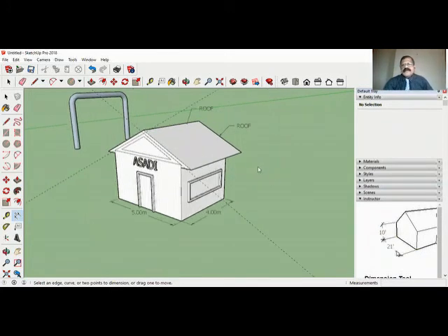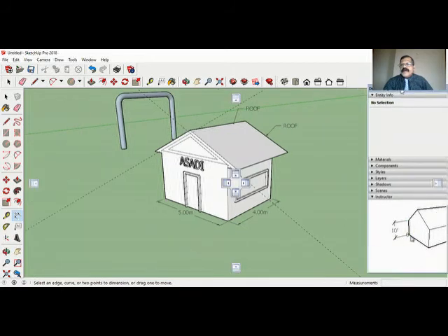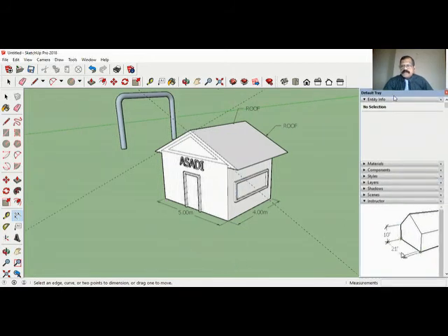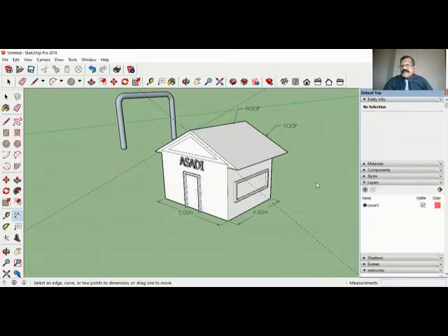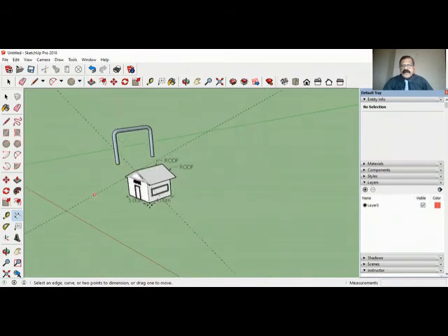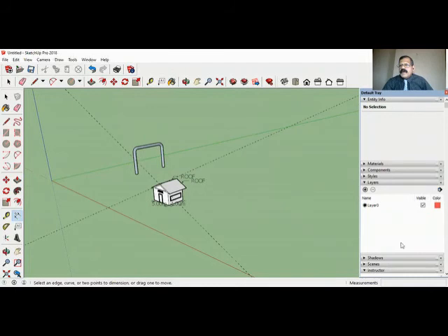Next thing is that, like in AutoCAD, there are layers here. Now everything was drawn in the zero layer. So what I will do is make a new layer. Just click the plus to create a layer. Let's say rectangle.